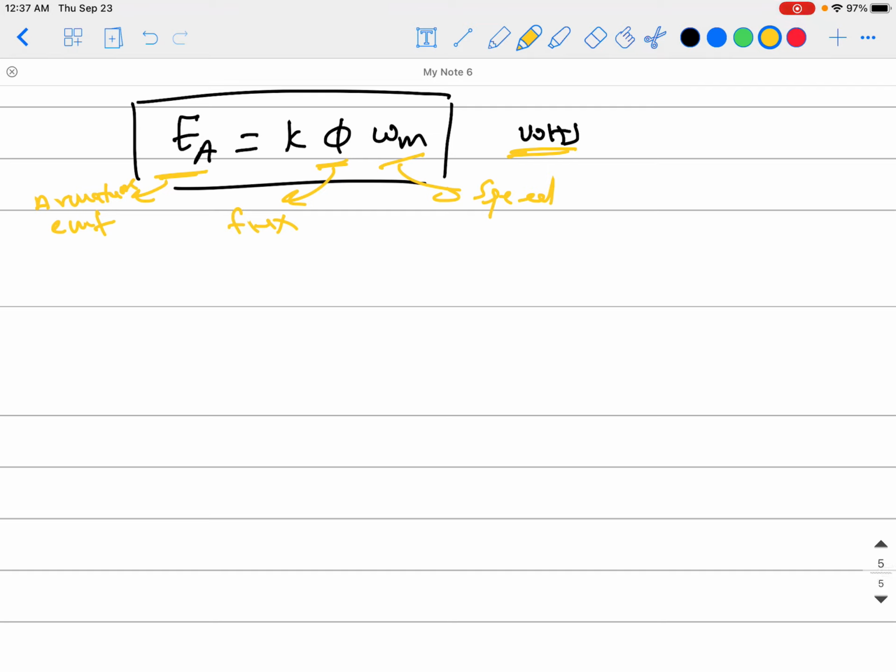What about quantifying the torque, if you're talking about a motor? Like we said before, that will be the same idea. The average torque is basically R L B average I. Remember this equation? B L I R, the torque coming from a single conductor. It is the same idea that this torque will be like this, and we will be just looking for the average value of it, T average.